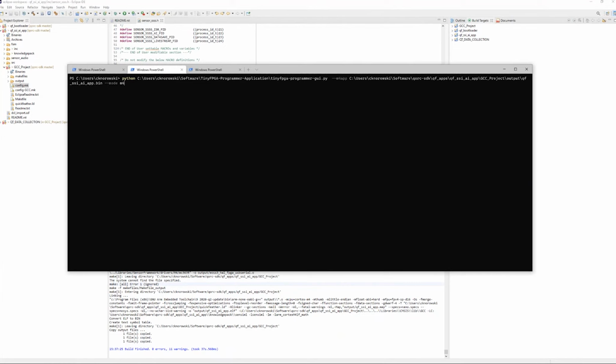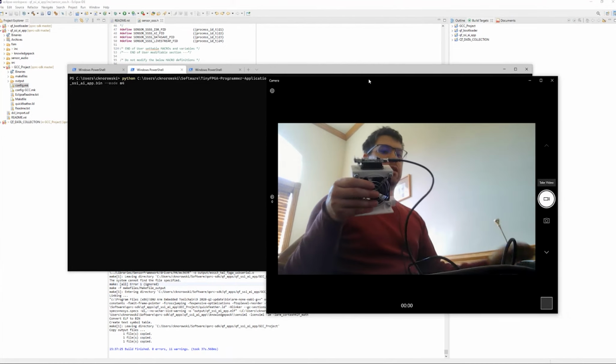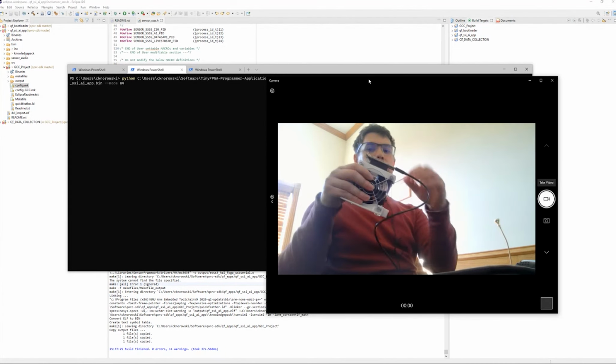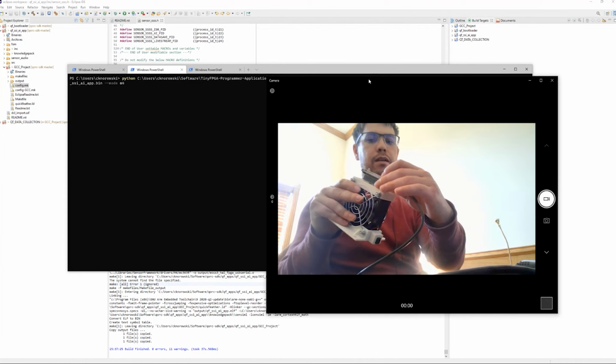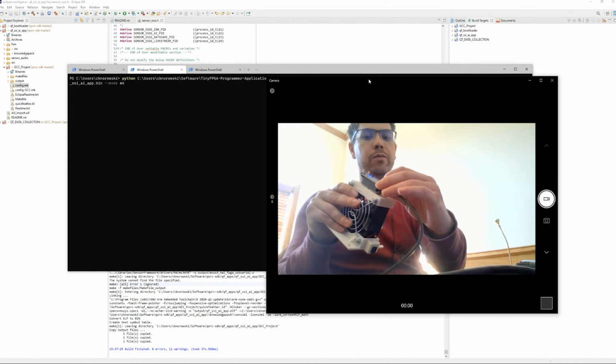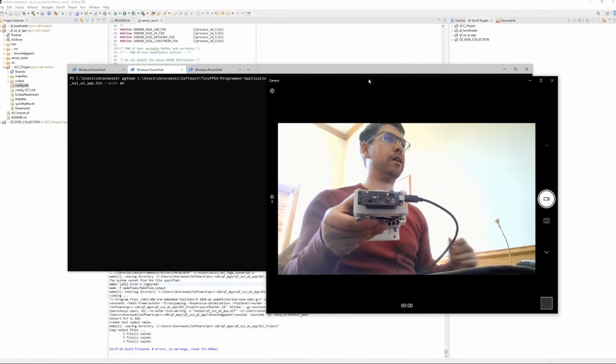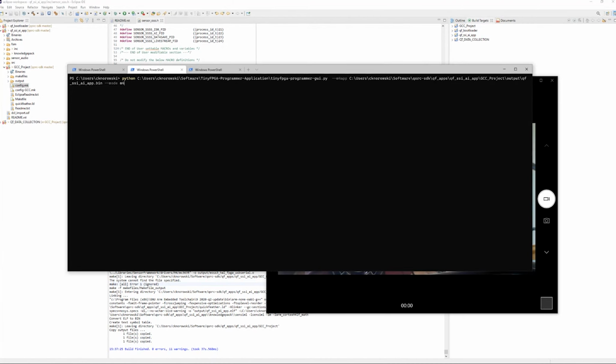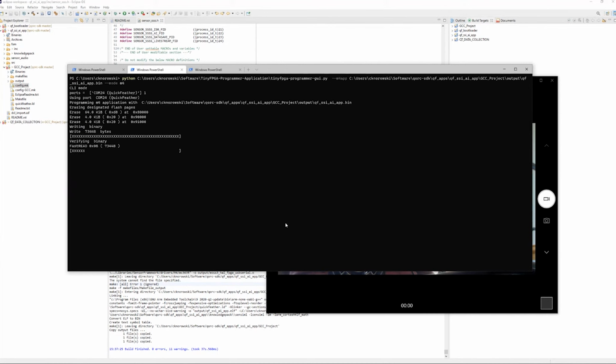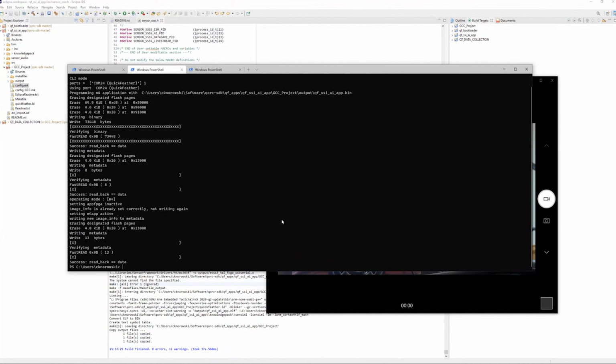And so before you do that, I just connected the cable. So you want to put it into flash mode. You click the reset button, and then you click the user button, and now it's blinking green. So I know I can flash it. Okay, so we're going to flash the board. And all right, now it's flashed. So our program is on it. And then I'm just going to go ahead and click the reset button on the board. And now it's powered on.